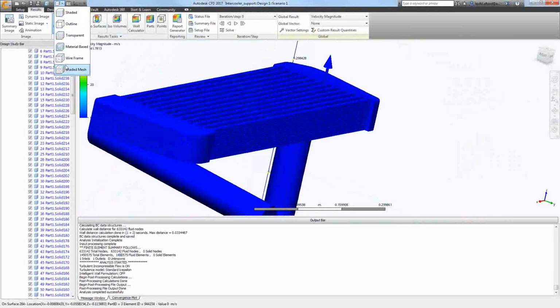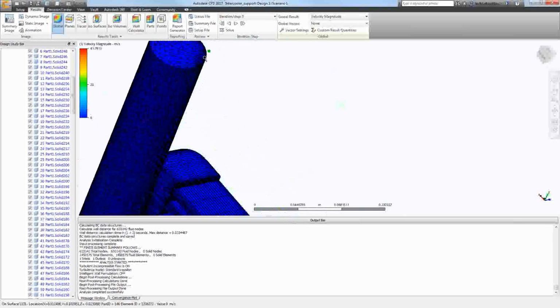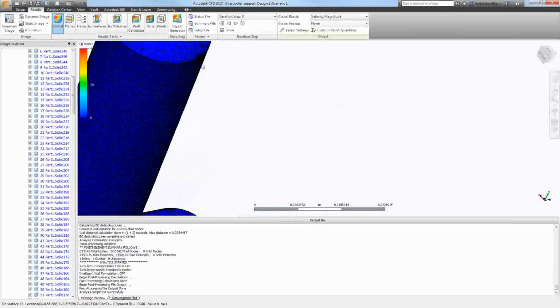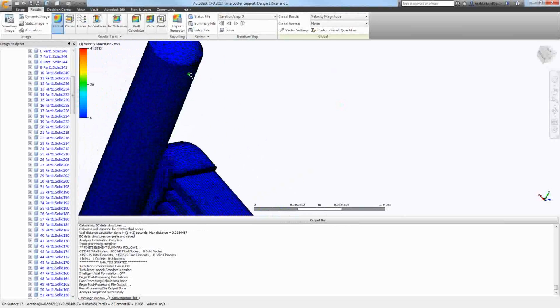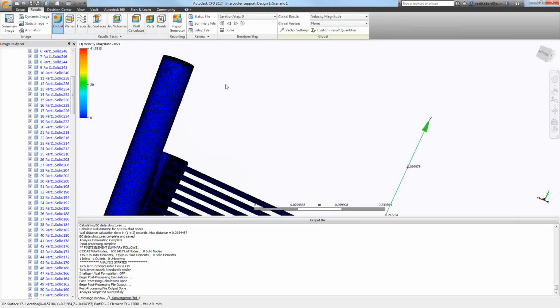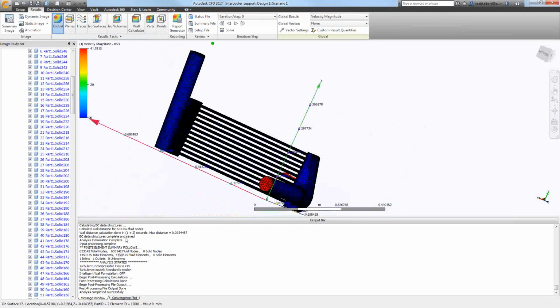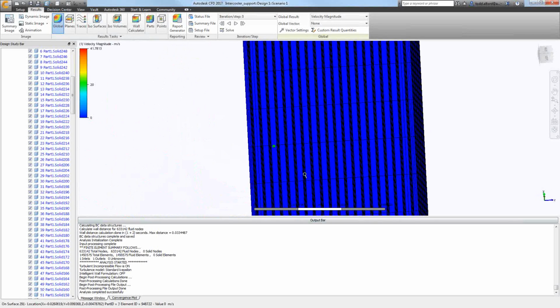I just meshed this right before the webinar, so I didn't do too much. I auto-sized it, and you can see that I was lazy. The geometry definitely still has some weird things on it, and this mesh is way too tight for just a simple channel. Amal did the right thing and cleaned it up, but I didn't. I was lazy. But I still got to 1.5 million elements, and I have all of the channels.